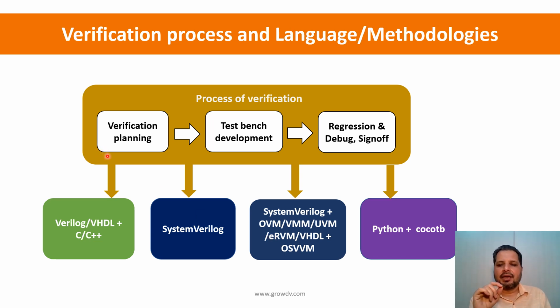For example, if I were to execute the process of verification using Verilog or VHDL, these languages do not have very good support for randomization. So I might rely on fewer random test cases and more directed test cases.